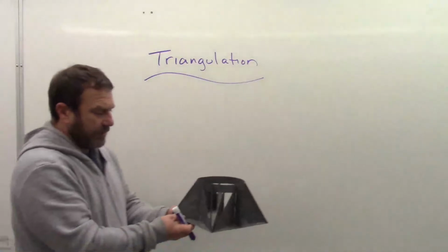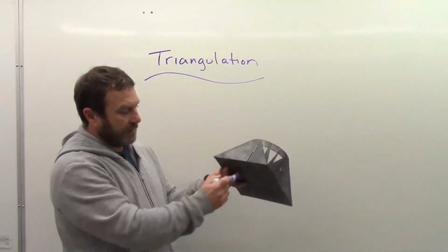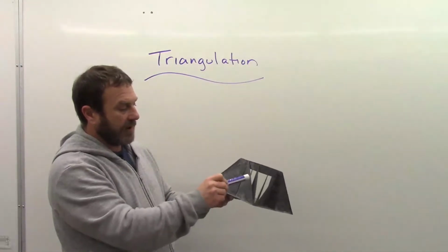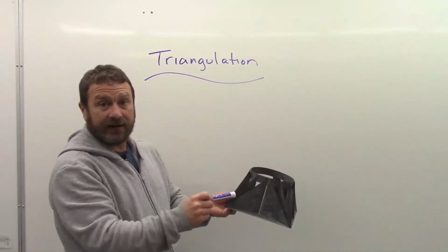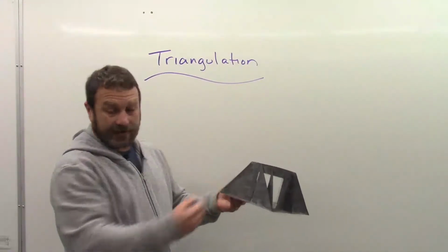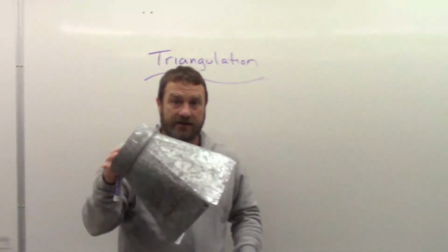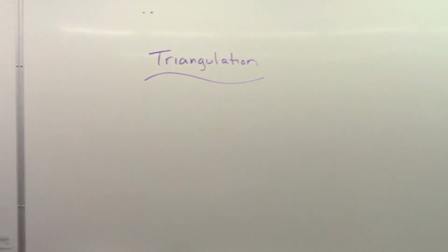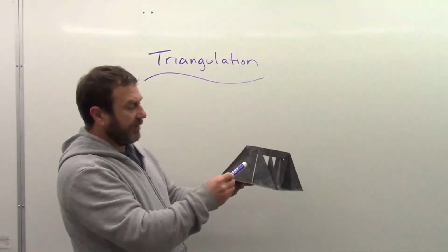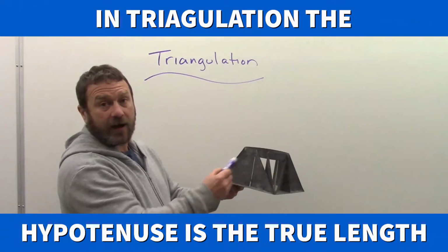Now, if we break down a square to round a little further, we come up with something like this. It's still a square shape and a round shape. And this is just a sample showing the triangles that make up the fitting. It's showing us a full triangle instead of just the element lines that we would have in a part. So in this one, we're merely looking at the outside edges, which is what an element line is. I like to think of them as the bends. So this one goes a little bit further. It shows us the base of the triangle, the height, and then the hypotenuse. And the hypotenuse is our outside edge.